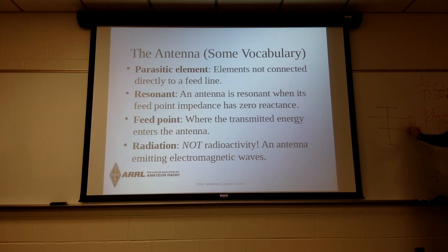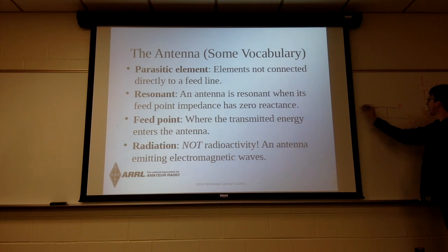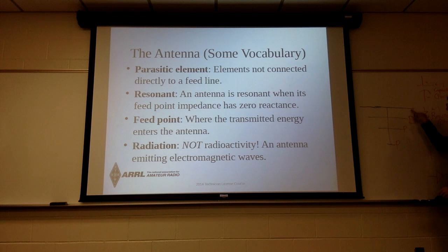If you're trying to draw a Yagi, the undriven one in the back, the parasitic one, should be longer than the driven one by very small amounts of a wavelength. This is the reflector. You won't have to do it for this class, but look up Yagi design. You can get all the figures out. But we call this the reflector, the driven element, and the parasitic.